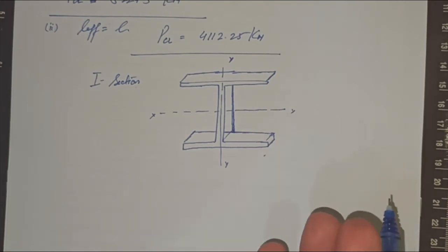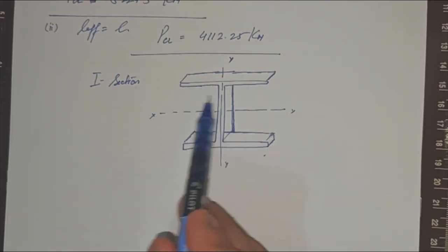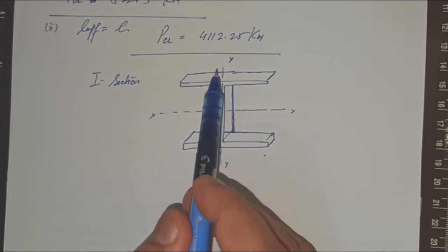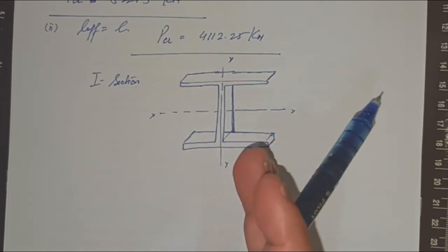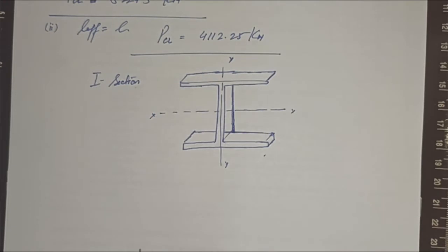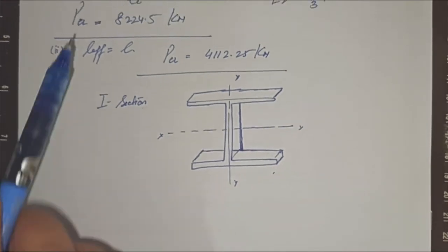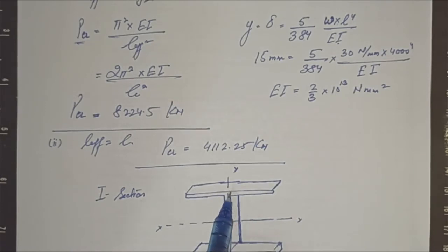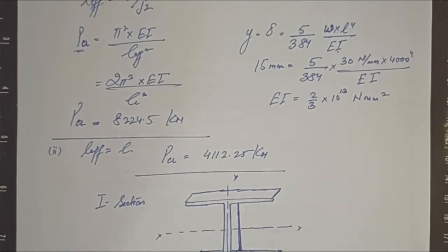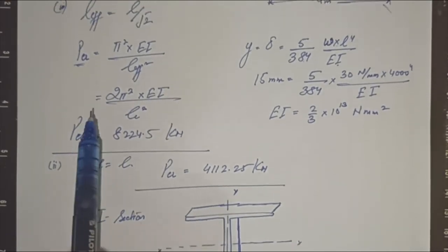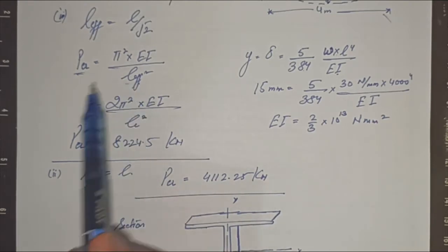So to obtain the least one, you have to find the moment of inertia of the sections, obtain them overall, and then make a decision on the moment of inertia. The second thing is to check the conditions you may be experiencing, since L effective will be based on that.